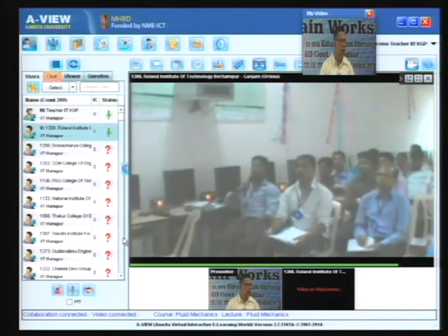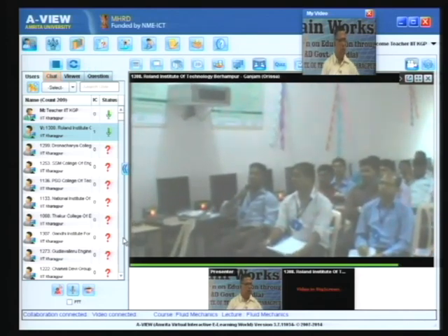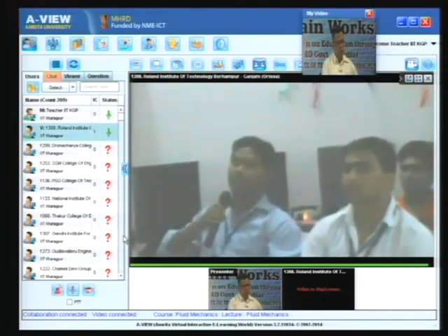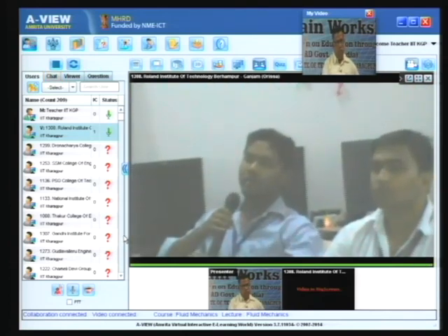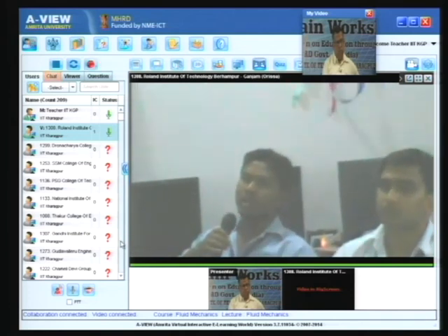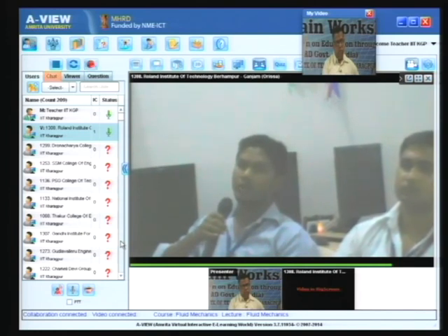Sir, in calculating the center of pressure, we are using the relation h bar equals x bar plus Ig divided by A x bar. But the x bar is taken from the free surface to the center of gravity of the body, but we are locating the h bar below the center of gravity. Sir, how is it possible?